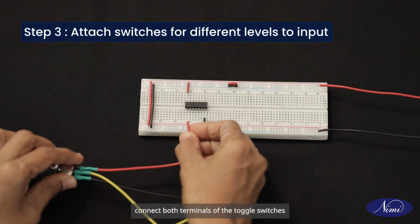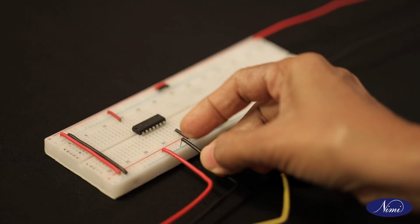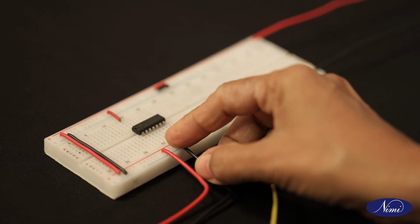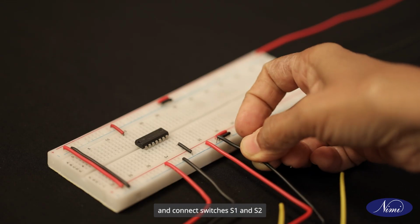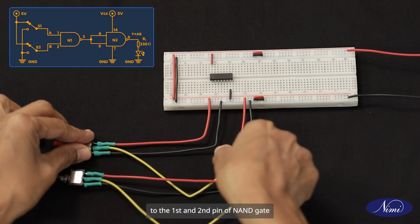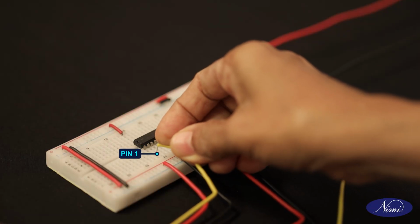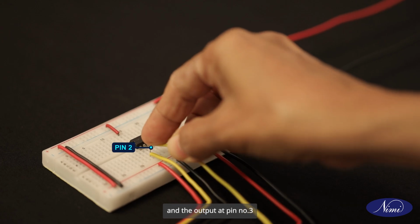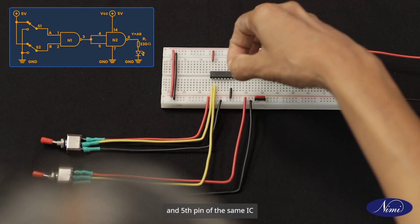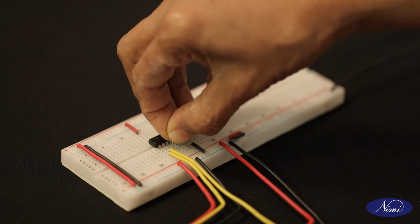Moving on to the inputs, connect both terminals of the toggle switches to the power source and ground. And connect switches S1 and S2 to the first and second pin of the NAND gate. And the output at pin number 3 is connected to both 4th and 5th pin of the same IC.